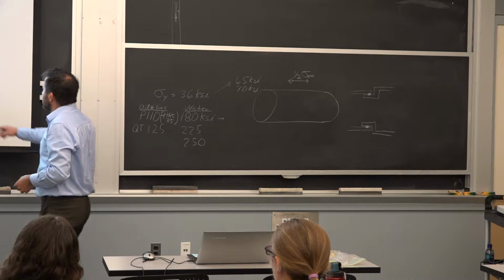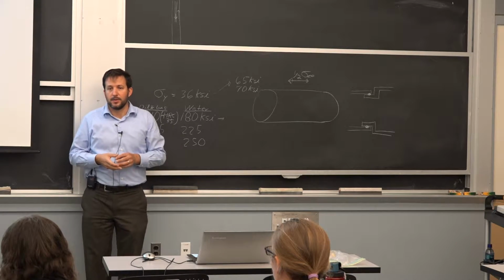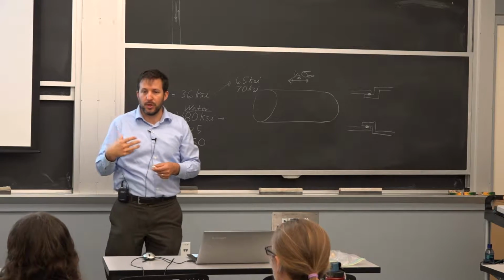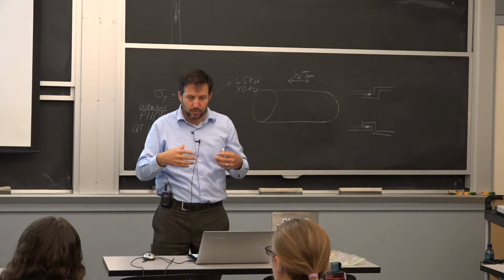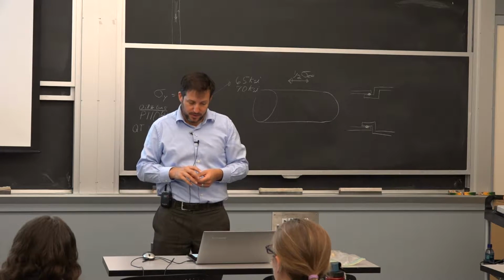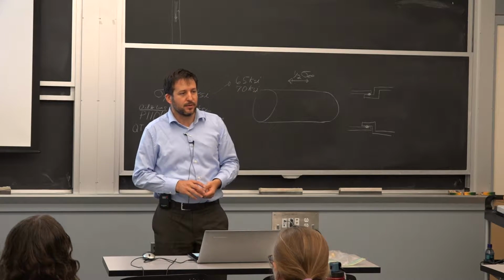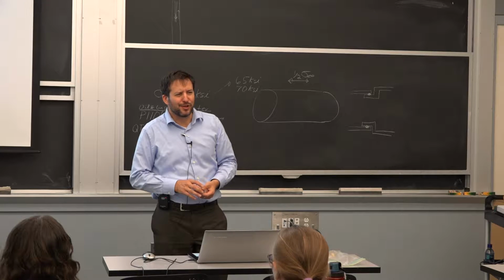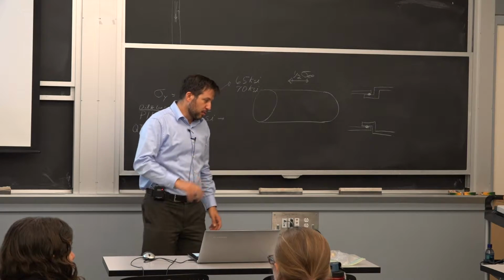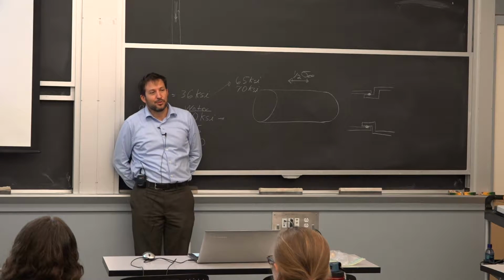You see here the martensite, but it looks a little different because it was tempered. There's still a little bit of a history of the needles that we saw in the quenched composition, but it did go through a diffusion process after the fact to make it also ductile and tough. That's really where the compromise is. Any questions on the self-drilling fastener? It's used a lot. Is it similar to what they do for drill bits? The drill bit, that's a good question. The drill bit a lot of times will be low ductility through the core.